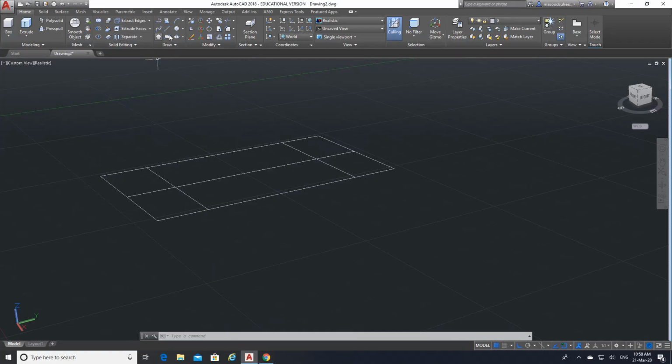Now let me come here. Where is the circle? Circle command is here. Center and diameter. Just go select the center, diameter is how much? 16. And then one more circle, go here. Diameter is how much? 16. Okay. I have got the diameters. Now what do I need? Do I need these lines? I don't need them. Just get rid of these lines because they will give trouble when we do the extrusion.